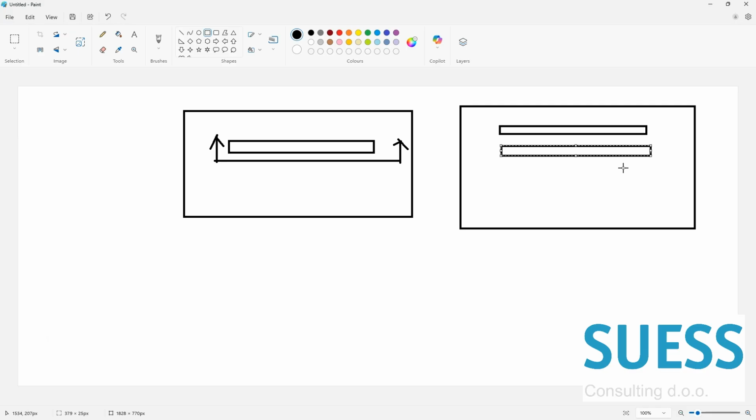And why I told you that we are also checking the overlap of the elements, because we used to have a situation like this when, for example, we had some small overlap, 2 centimeters, 3 centimeters, usually in places where we have some wall. So you stop the cable tray on one side, and maybe on some other elevation you continue, and then the script will detect hundreds and hundreds of problems, in quotes, where you have an overlap of the elements of 2-3 centimeters.